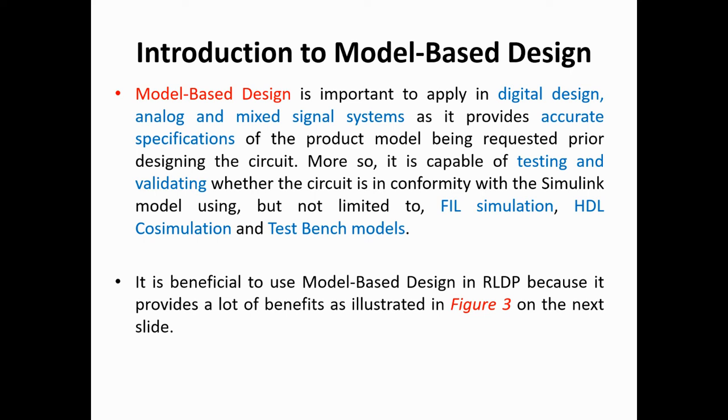Basically, FIL or FPGA-in-the-loop and HDL or hardware description language co-simulation are just simulation tools that you can use to compare your Verilog models or VHDL models with your Simulink models.